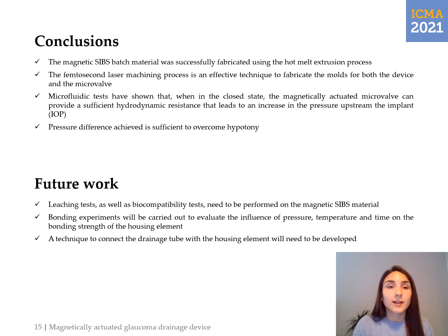Now, conclusions. The magnetic sieves batch material was successfully fabricated using the hot melt extrusion process. The femtosecond laser machining process seems to be a very effective technique to fabricate the molds for both the device and the microvalve. And the microfluidic tests have shown that when in the closed state, the magnetically actuated microvalve can provide a sufficient hydrodynamic resistance that leads to an increase in the pressure upstream the implant, which corresponds to the IOP. So this pressure difference achieved is sufficient to overcome hypotony.